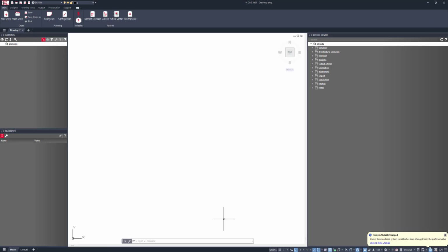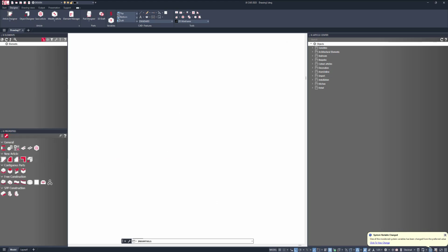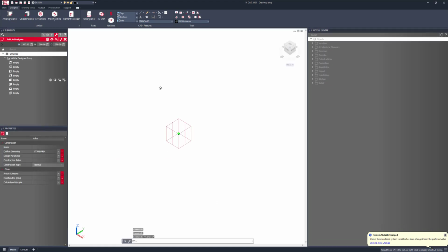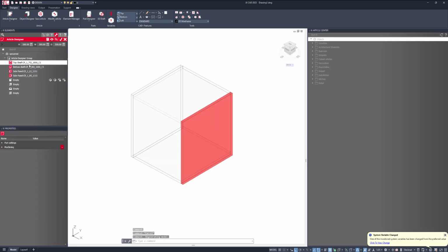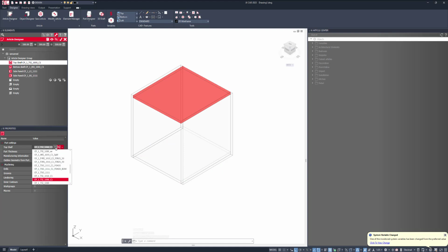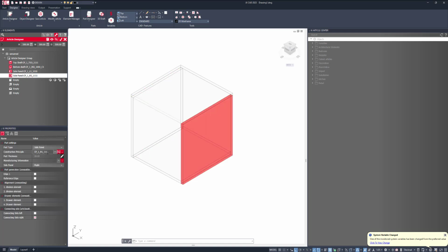So what we'll do now is swap over to CAD, go to Article Designer and set the height, width and depth of my product. I'm happy with my 500 by 500 cube. I can add in my top, bottom, left and right. I'll change my top to be an onset top, and I'll change my left and right hand side panels to just be edged on the front and back edge. So I'll say 1, 0, 1, 0. Same for the right hand side.